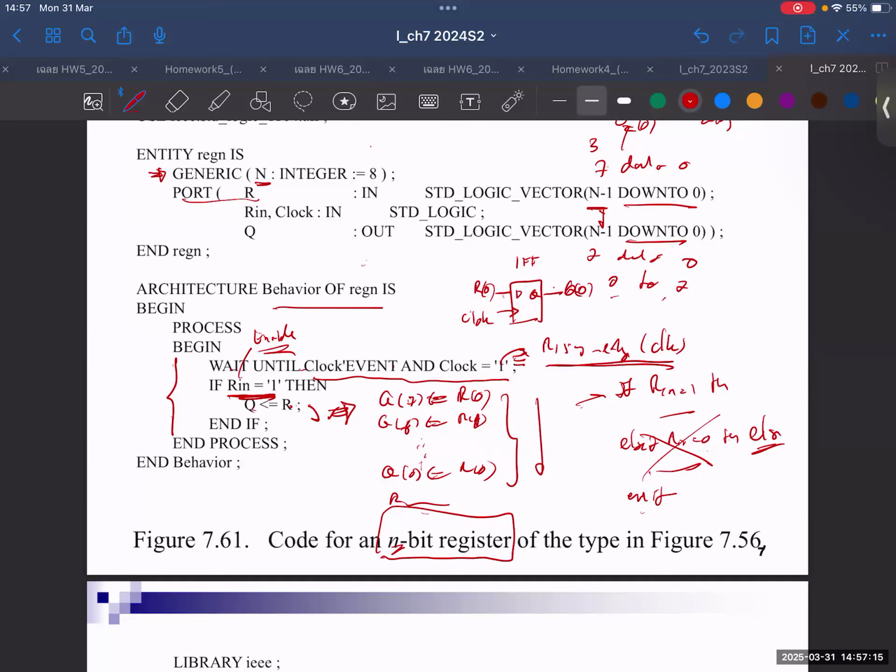Understand? Because it can be any state now. It can be 1, it can be 0, it can be X undetermined, it can be high impedance. You tell them what to do when this is 1 and what to do when this is 0. But what happens when this is high impedance? Uh-oh. Understand? That's why you cannot use your mentality when you write software in VHDL.